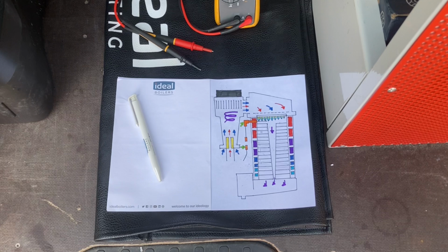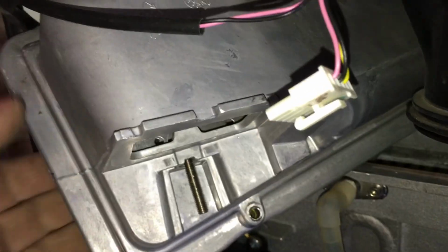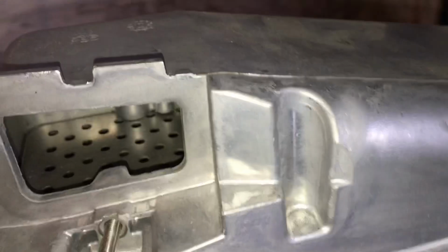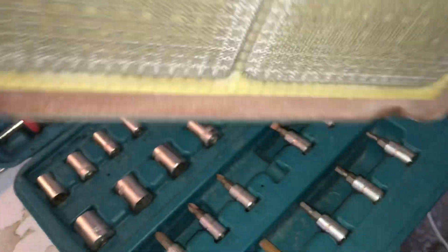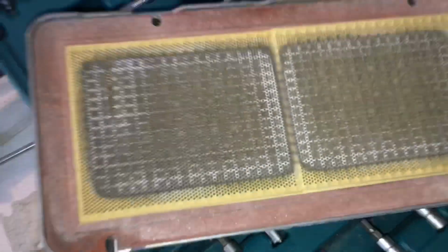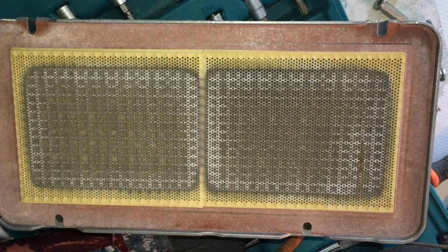It talks about something I've figured out myself, really: how to test for a blocked burner. I spoke in the last video about how once you get air particulates or anything else stuck in a burner, you aren't going to get it back out, and it's difficult to test whether the burner's blocked or not.